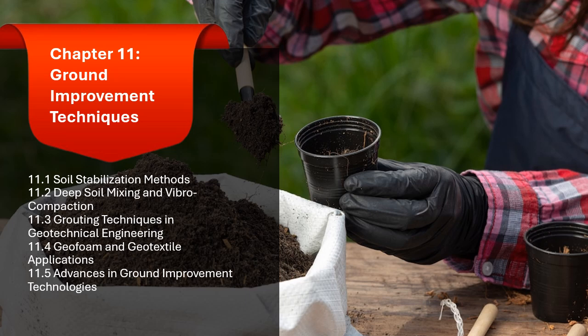1.3.4 Advantages of grouting techniques. Increased strength and stability. Grouting improves the strength of weak soils, making them more stable and capable of supporting heavier loads. Reduced permeability. Grouting helps to decrease the permeability of soil, preventing the infiltration of water into structures or foundations. Cost-effective.